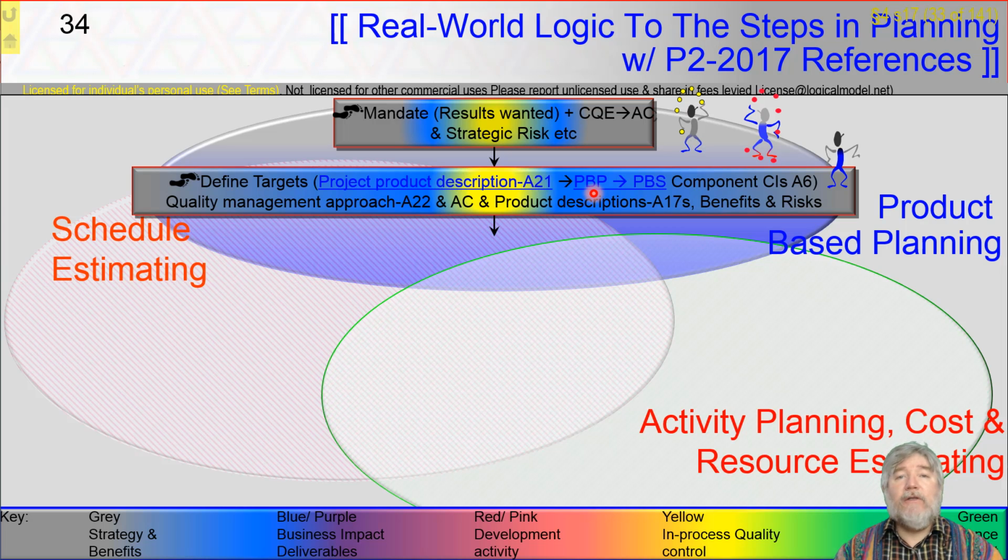So if I'm going to build a house, I have to lay drains. When I lay drains, there will be a building code wherever you are in the world that says what the rate of fall is to ensure that the water runs through that drain and we don't get muck building up in the drains and blocking them. And that building code will be the conditions of satisfaction or the acceptance criteria that are required.